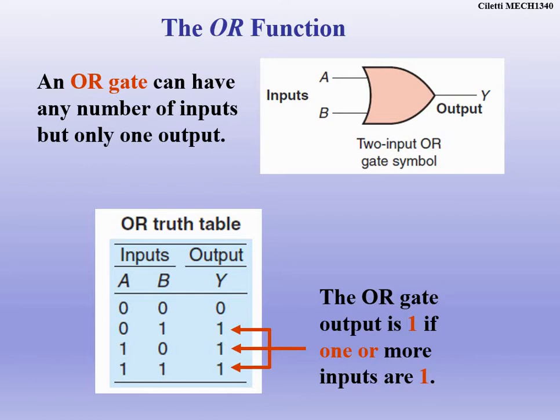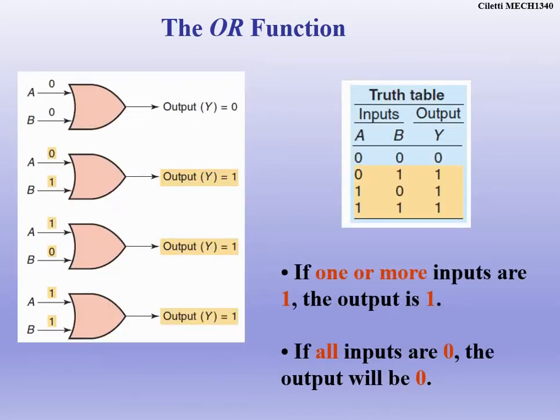So these are a 74LS32 logic gate when we do breadboarding and things like that. Okay, and just like we did the last one, you can analyze each possible combination here that goes through the truth table and shows when A is 0, when B is 0, when A is 0, B is 1, so on and so forth. You can kind of figure out how that creates the table for the OR function.